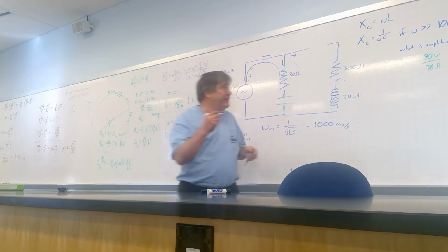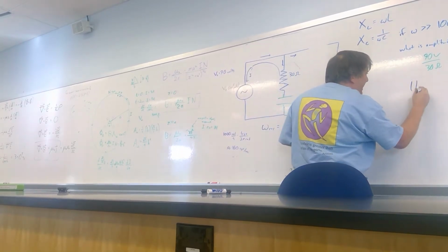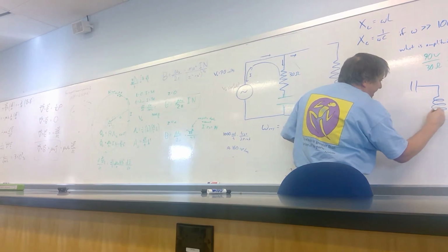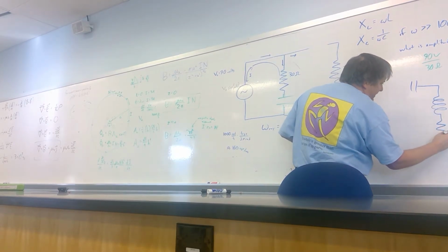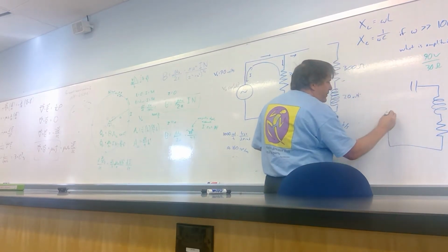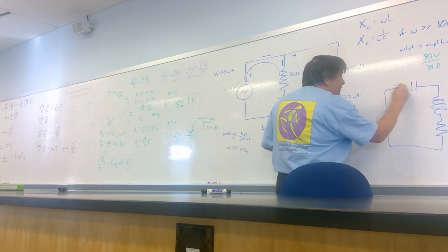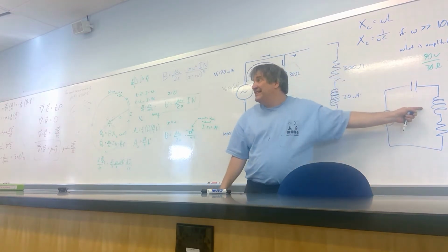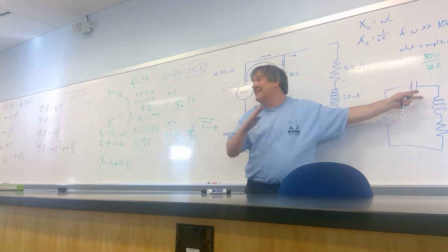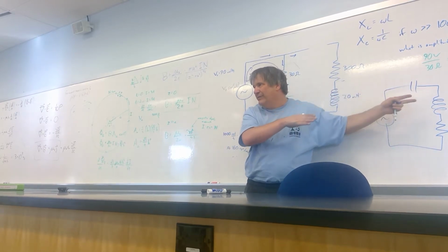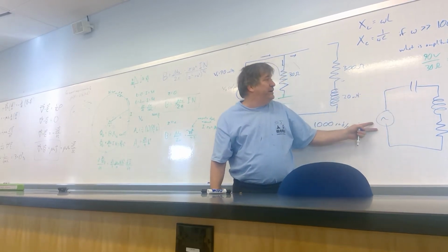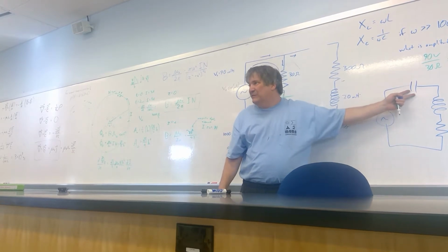If I was doing series, then you could say, you know what? If either of these 2 devices, so if I'm just doing my standard series LRC circuit like this, as the frequency goes to infinity, this guy becomes such a huge impedance that the current is pretty much zeroed out all over the circuit. As the frequency goes to 0, this one becomes a huge impedance.